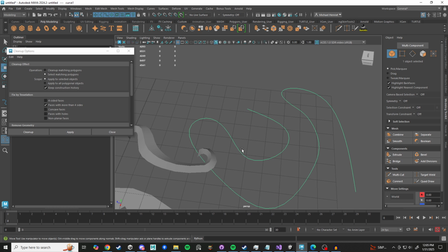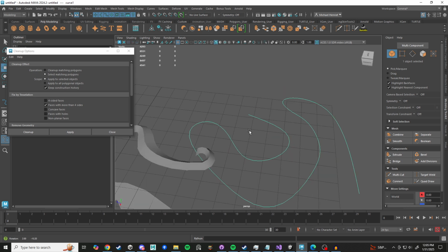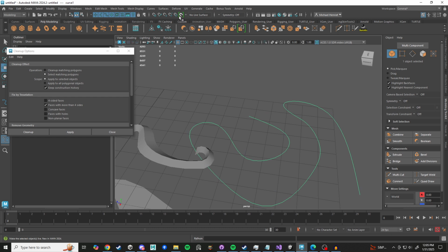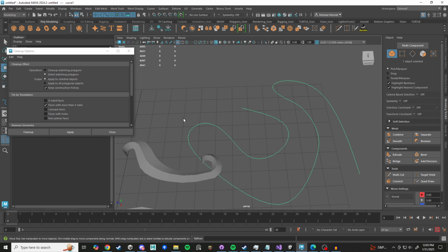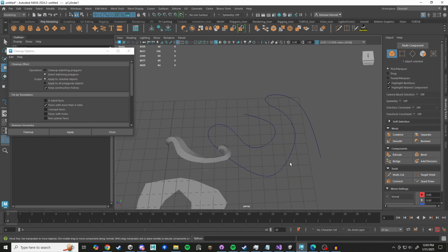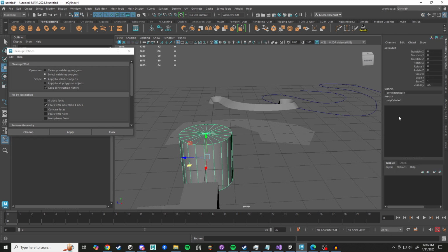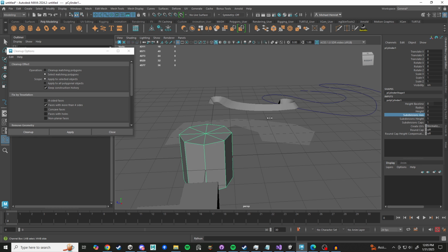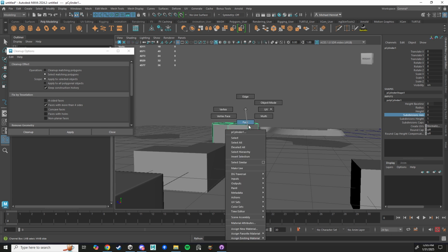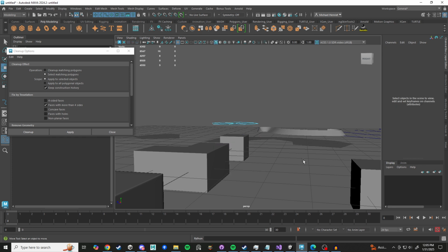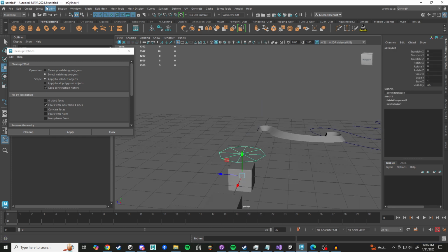And that was just left clicking, and they usually like to stick to the grid. I bet if you turn on live surface or something, you could make a live surface be the thing that gets the curve plastered on top of it. But what I want to show is that you can create, let's make a cylinder. And then I'm going to change the subdivisions. Let's just do 8 so it's not super heavy. And then I'm going to delete these. So now I have this. I'm going to do modify, center pivot, so it just snaps the pivot to the center.